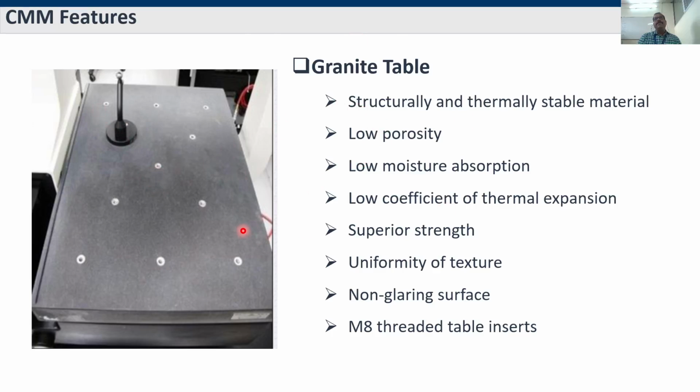Maybe you know that in the moving table or moving arm, there are two types, top mounted and side mounted. Inside, they might have guideways, but in top mounted, the CMM structure is placed on top. But here, what is used in our lab is a fixed table and moving bridge type only.